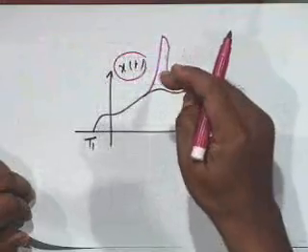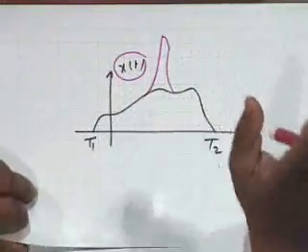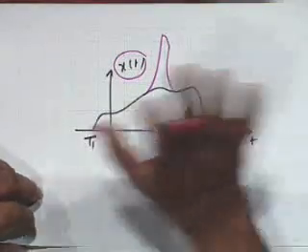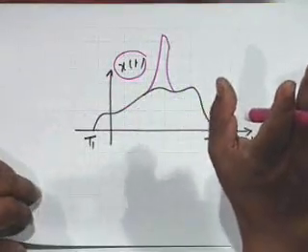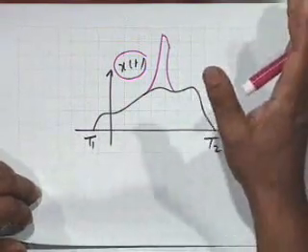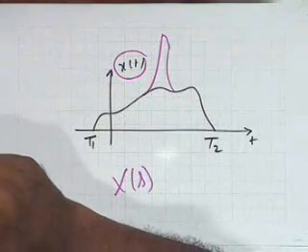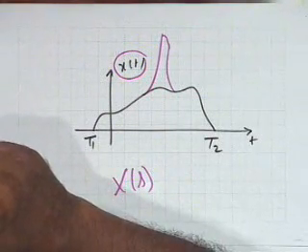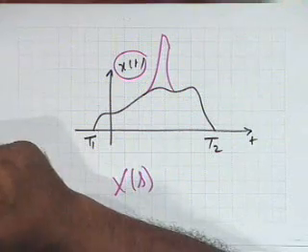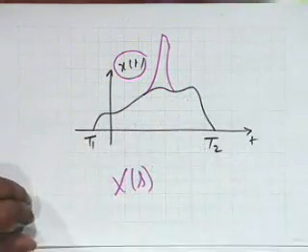So, for a finite duration signal which is well behaved, what does well behaved mean? Qualitatively, it does not blow up anywhere. For a finite duration well behaved signal, the complete S plane is the ROC. What does that mean? It means that capital X of S shall not have any pole, it shall have only zeros. We will consider the other two ramifications of this property next time.